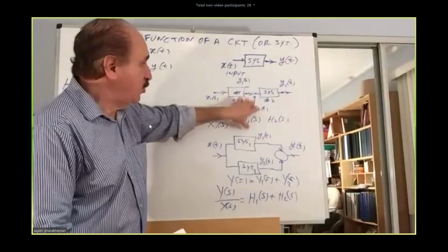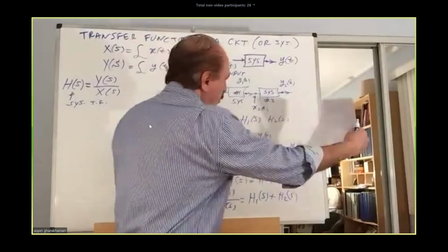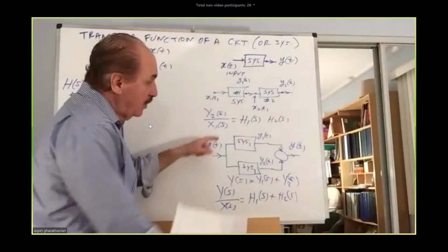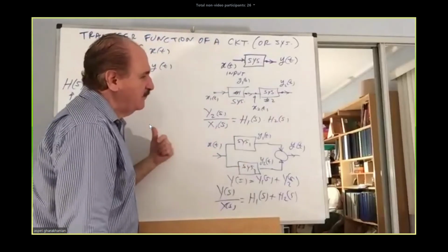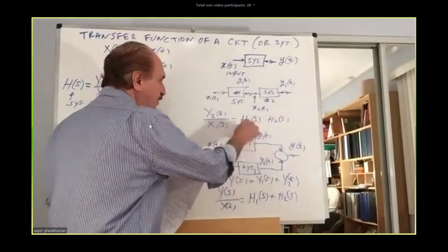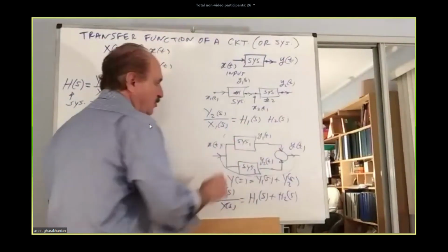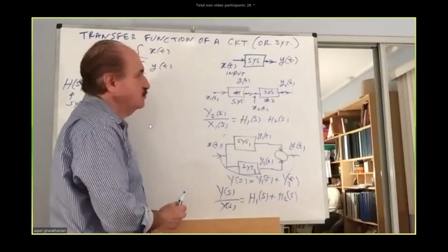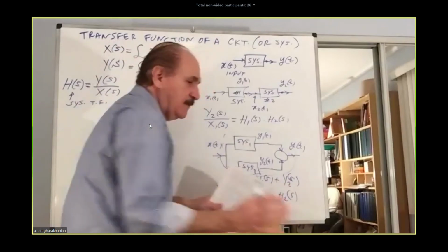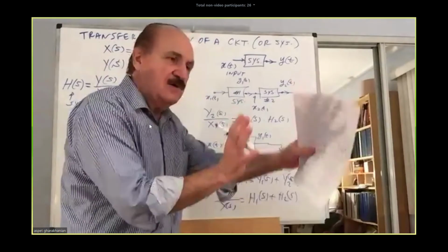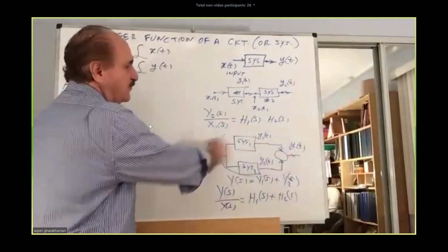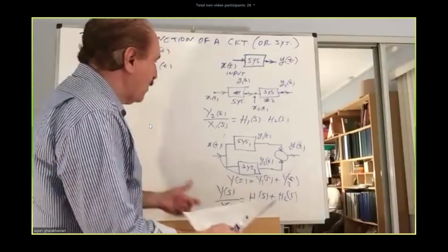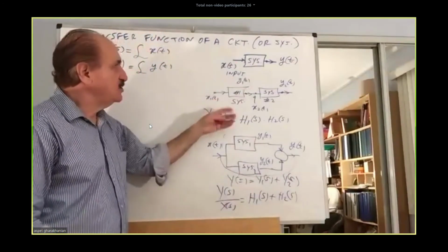But if you have poles and zeros, now you get a more complex one, plenty of zeros, plenty of poles. If they were adding in this fashion, and you want to account for this whole thing with an equivalent transfer function, you wanted to describe it with a single one, this will be the single one, the sum of the two. So you will take the two functions, you will add them, summarize them into one unique function. And that will be the equivalent of the transfer from one point to the other. That's it. So this is the story of the transfer functions.